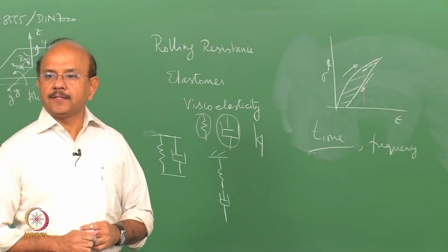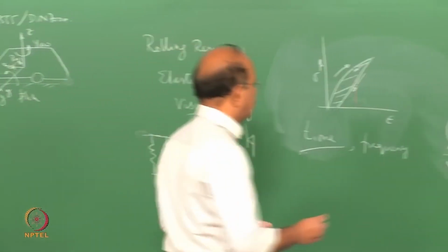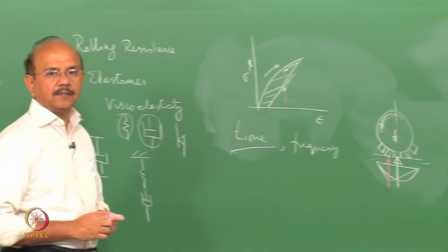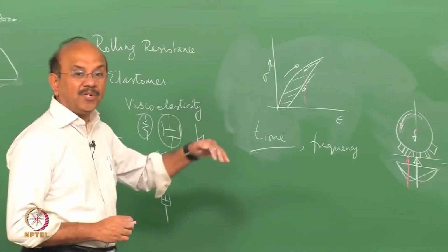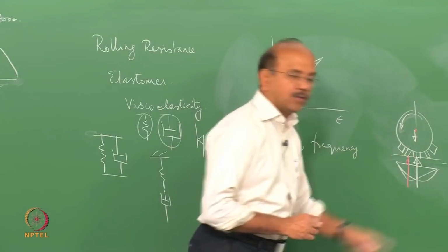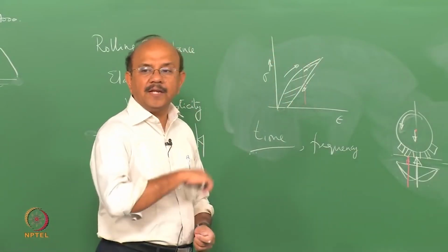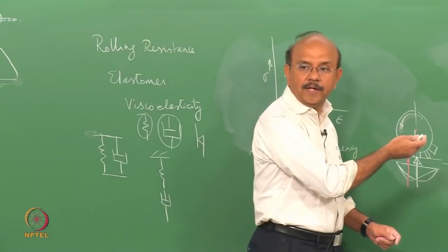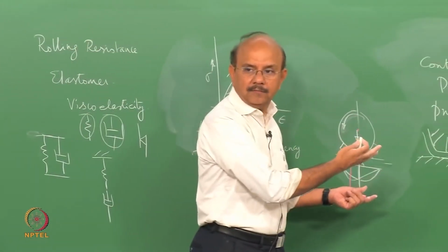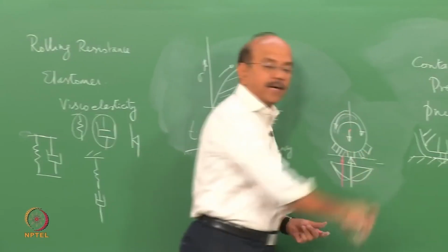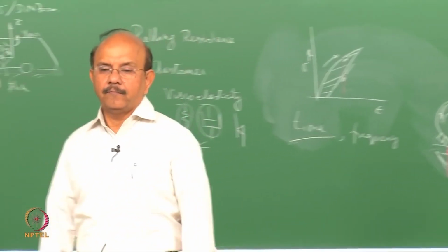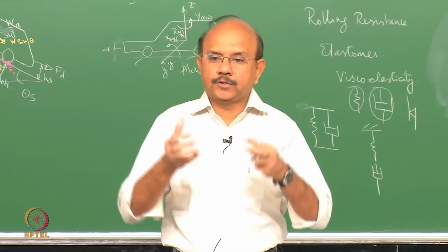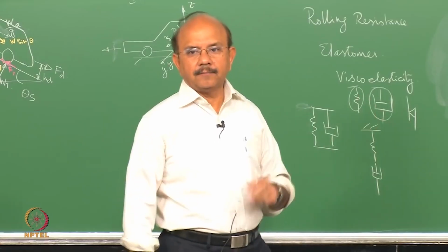When it acts away from the center, then if I now look at that load with respect to this center, not only am I going to equilibrate this load with this force, but I am also creating an additional effect, correct. So, what is that additional effect? That will be a torque, or a moment, acting like that. Watch carefully that the moment is now going to oppose the motion of the tire.